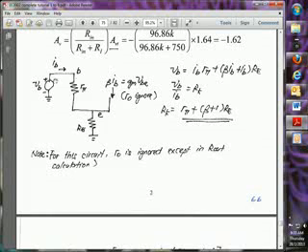And in order to solve for VB divided by IB, simply write a KVL equation down. VB is equal to the voltage drop across R pi. R pi times IB is the voltage across R pi plus the voltage at this point. As the current IB flows down, beta IB also flows down. The total current flowing across RE is beta IB plus IB.